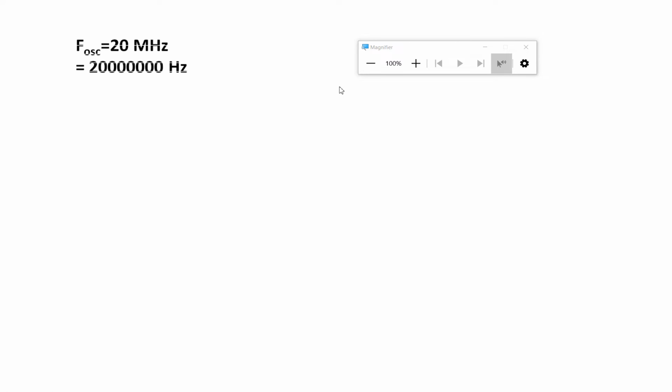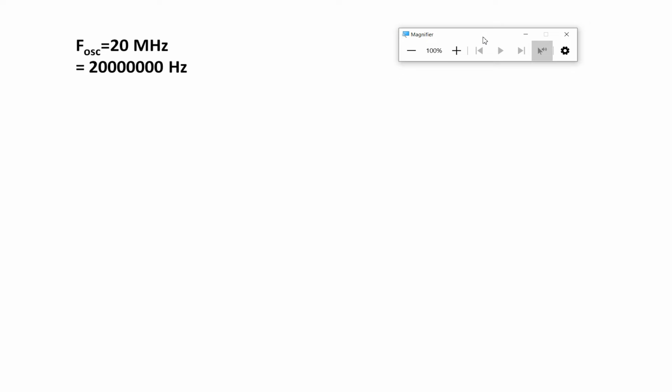Now take a look here. First of all, the crystal we are using, we must know the crystal. I am using a crystal oscillator of 20 megahertz. And then the next thing is, what is the CPU frequency? CPU frequency is divided by 4. It is the internal architecture. Whatever crystal you select, you must divide it by 4. If it is 16 divided by 4, it will be 4 megahertz. So this is internal architecture, it cannot be changed. This can be changed. You can remove or attach another crystal, or you can use the internal crystal depending upon your requirements. Now the prescaler, as I already showed, I had selected 1:256.